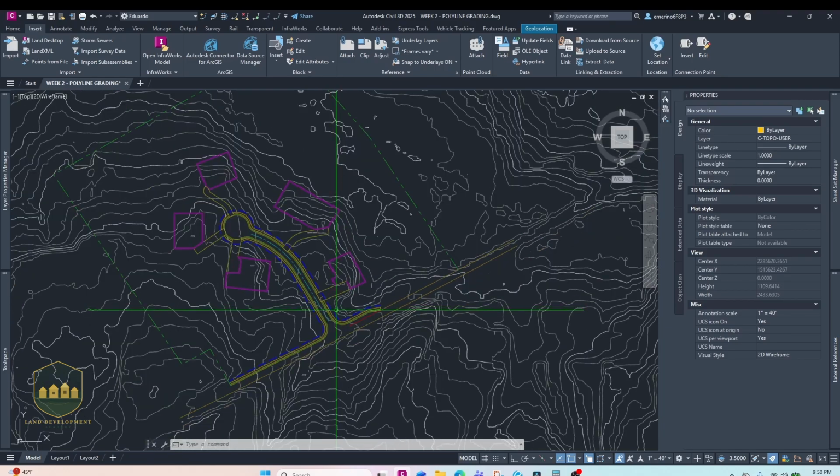what I want to do first is recognize my constraints. Always, always, always know what my constraints are. Now, this site plan is highly simplistic. Normally in the real world, we have easements, we have wetlands, we have buffers, we have setbacks, we have a landscape strip, we have zoning conditions, and we have a lot of stuff to consider, a lot of constraints. But this is week 2, so I don't want to overwhelm people.